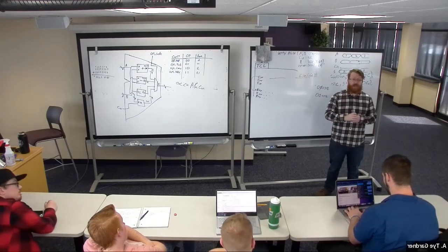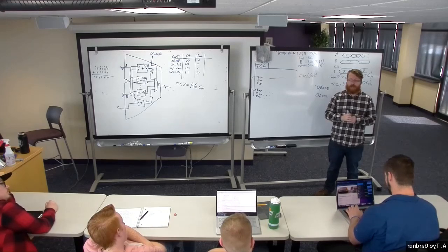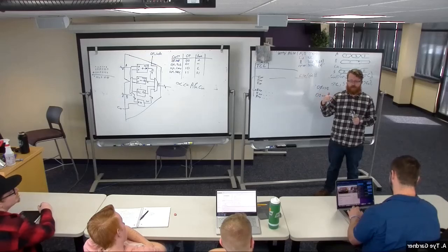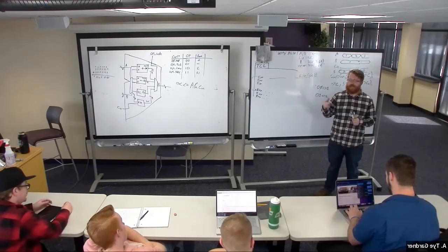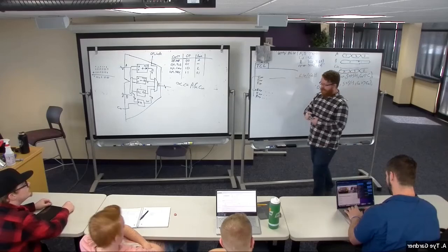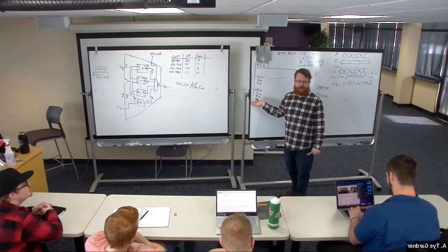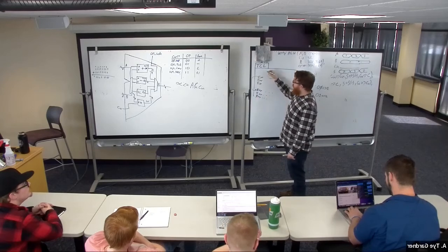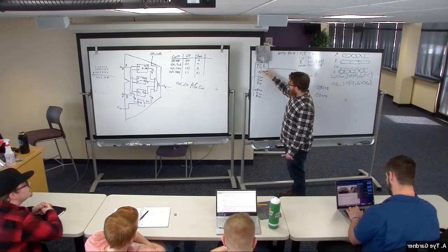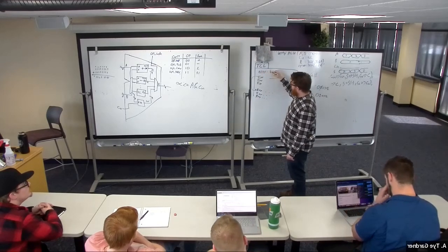Also, the nice thing is once you have your test bench up and running for the 8-bit adder, the code that I've provided for you that runs through and tests all possible input combinations will also show results here. If you don't have any issues, the TCL console will be blank and won't do anything. If you do have errors, it will say something like error colon bad sum.